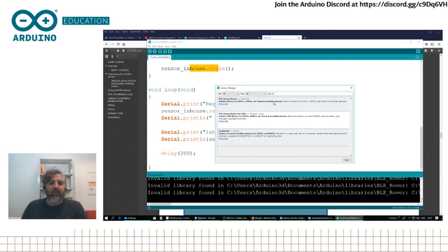This is something that you will realize as you go. More and more sensors don't exist in isolation. They always exist with something else. For example, accelerometers typically have an internal temperature sensor because the temperature is used to calibrate the accelerometer so you get the right information. This is very relevant because more and more sensors are going to be having this kind of mixed interfaces. So we're going to get this library from Adafruit and install it, and then just run one example, and with that we'll have seen the last sensor of the day.